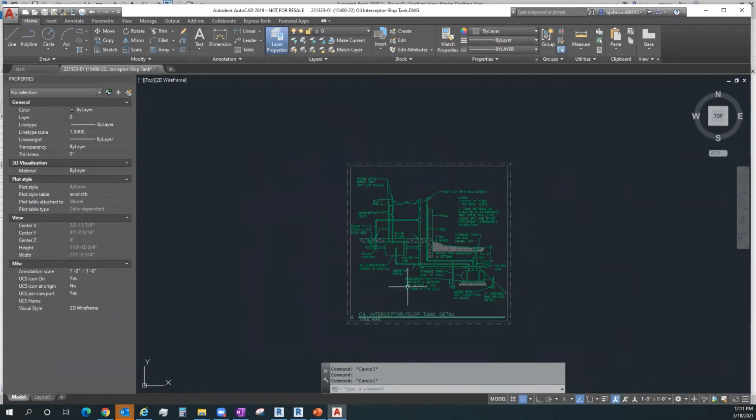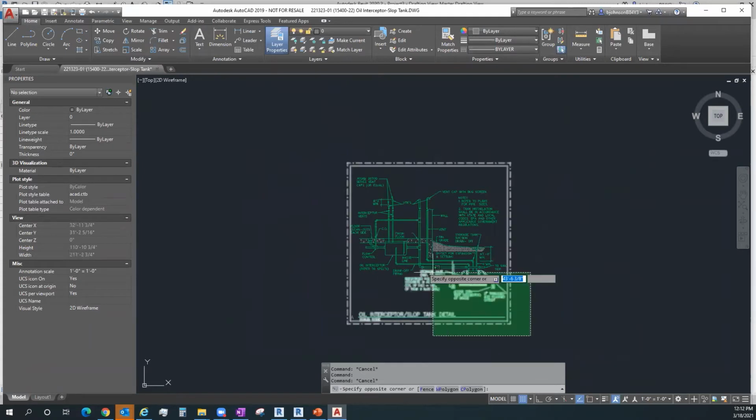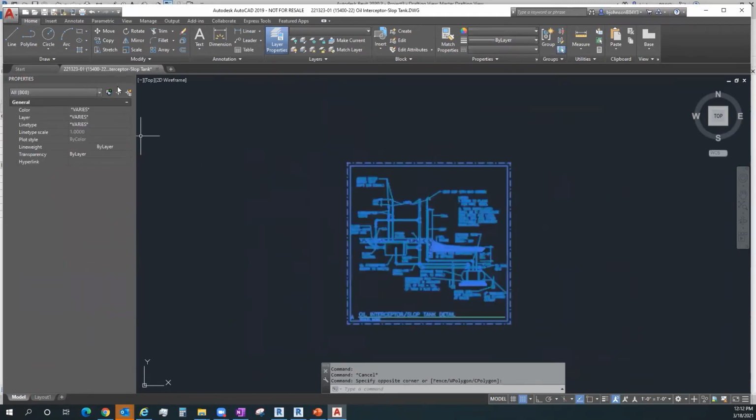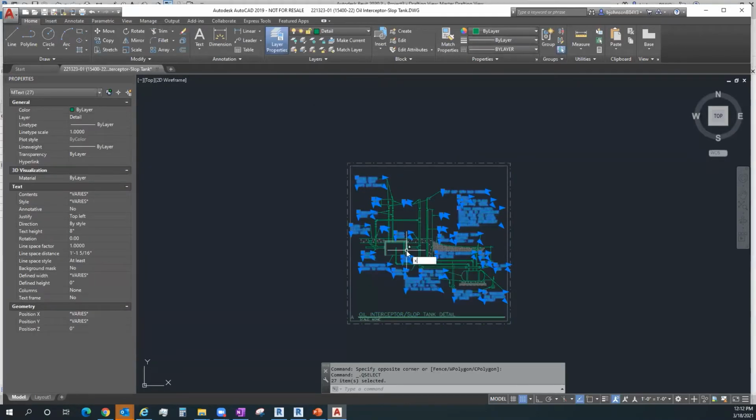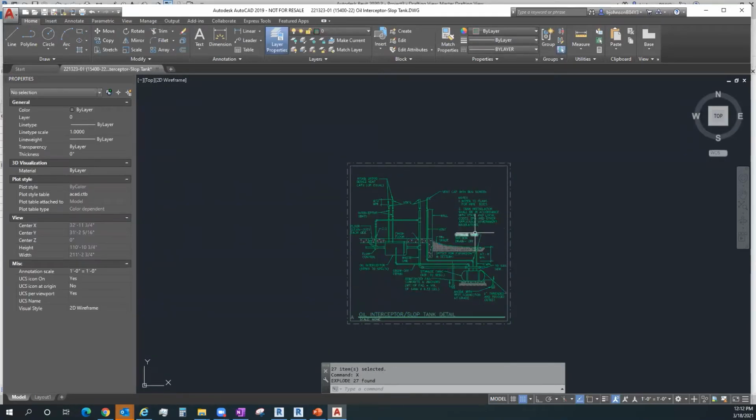So ahead of time, I could just swipe this entire thing due to my text being potentially strange. Go into a quick select in AutoCAD, find all of my M text and make it a selection set, hit my X enter for explode, and now it's all individual lines of text, which will be a little bit more cumbersome to put back together as one paragraph later, but at least I don't get these super wide text boxes that are very hard to manage. So that'd be some pre-work that I could do inside of AutoCAD first.